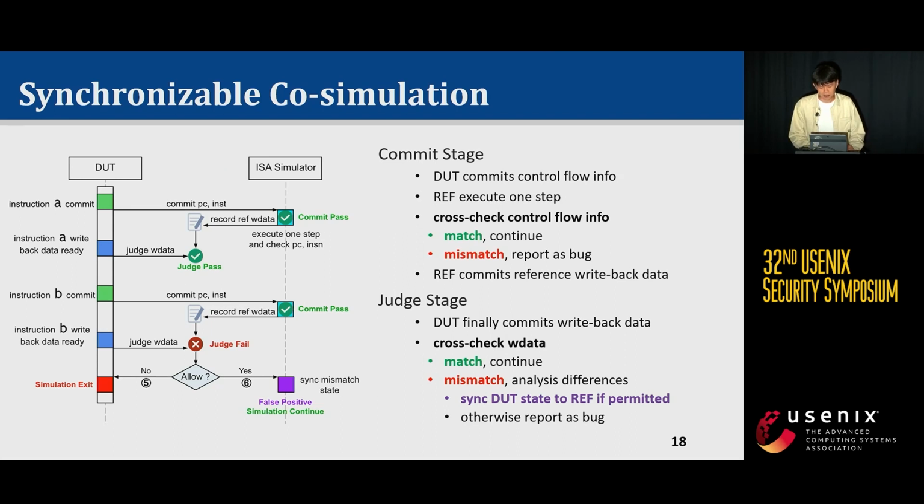And we eliminate implementation differences by state synchronization. To avoid introducing false negatives, we divide the state comparison into two stages. In the first stage, we only compare the control flow information to make sure the DUT and the reference model are executing the same instruction. And in the second stage, we compare the write-back data. If the results do not match, we further analyze whether it is an implementation difference. If yes, we will synchronize the DUT state to the simulator to make the simulation continue executing.